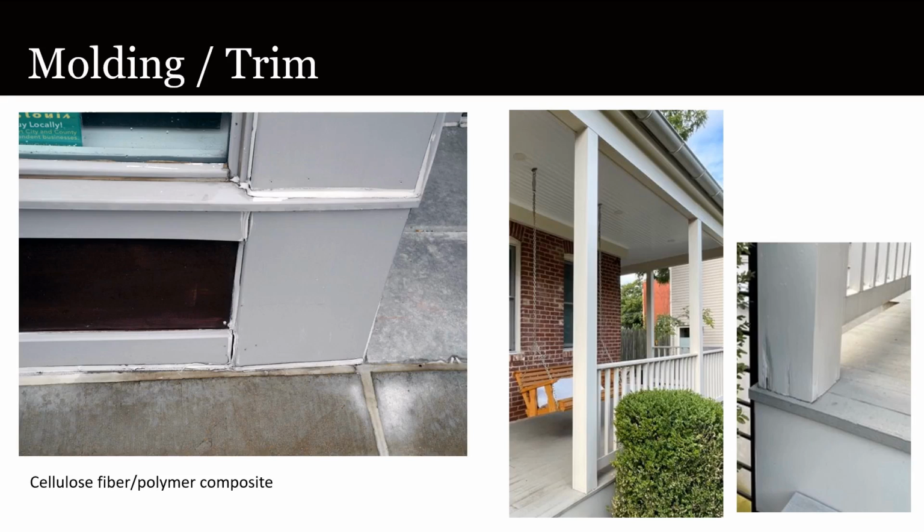While less prone to movement with heat, it is subject to moisture-related movement. And being isotropic, it can move more than wood over a long dimension. Such was the case illustrated by the storefront base on the left. The material must not have been thoroughly dry when it was installed because it clearly shrank enough to merit some remedial caulking, done very poorly and ineffectively.